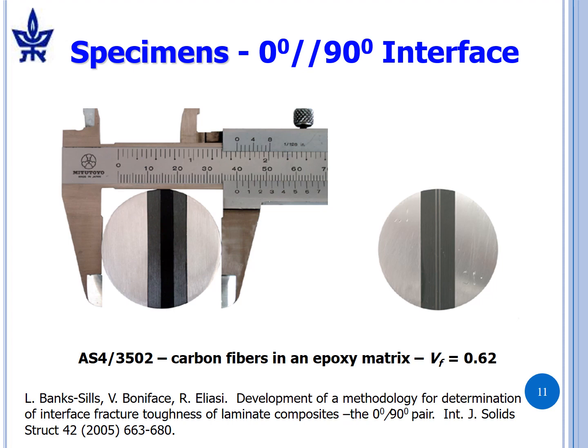And we have AS4 carbon fibers in 3502 epoxy matrix with a volume fraction of 0.62, a 62% volume fraction of carbon fibers. And here you can clearly see, in the right figure, the thin 0.5 millimeter thick layers of 0/90.